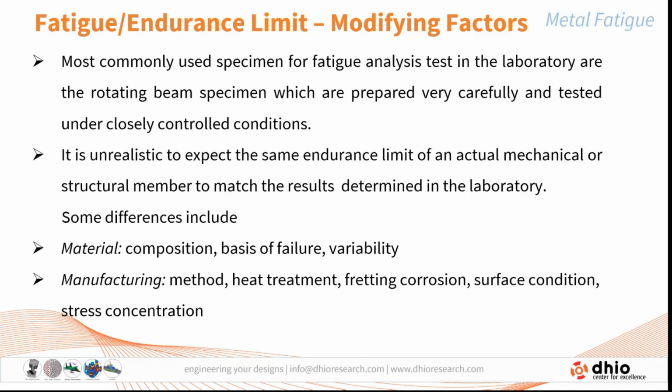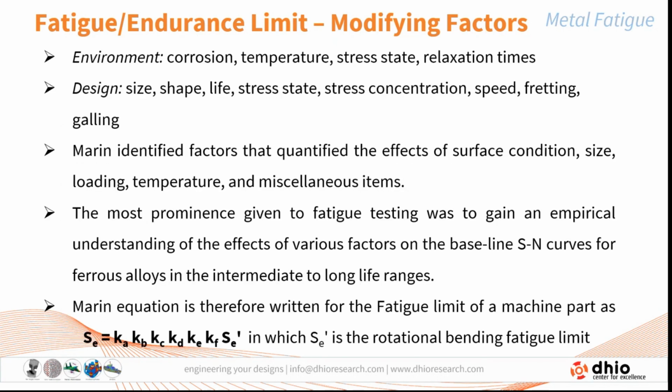So some of the things to be considered are the material, whether the composition is going to be similar to that of the standard test specimen, which is going to be the basis for the failure, and the variability involved in the material, how the material is going to behave. Also the method adopted for manufacturing, the heat treatment given, and the wetting, corrosion, surface conditions, and stress concentration caused during manufacturing have to be taken into account to make some modifications in the fatigue life of the component.